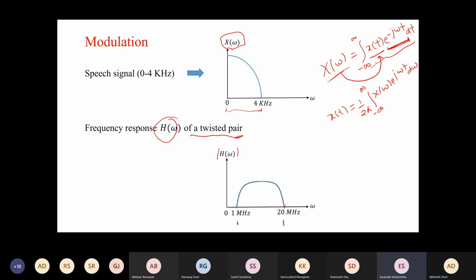In this equation, what are we writing? Here we are constructing a signal x(t), right? So this is the projection of x(t) along this. Now, actually this is taking the dot product of a vector with a unit vector. Here what we are doing is we are taking x(t) and writing it in terms of its projections. And how many bases do we have? Uncountable. Because omega takes values from minus infinity to plus infinity, we have uncountable vectors.